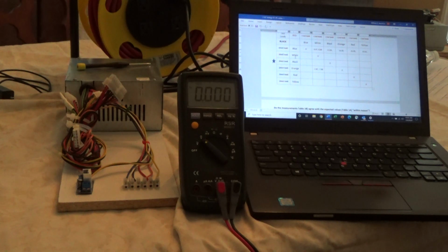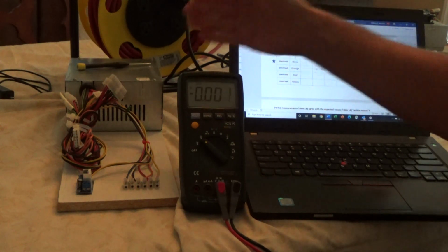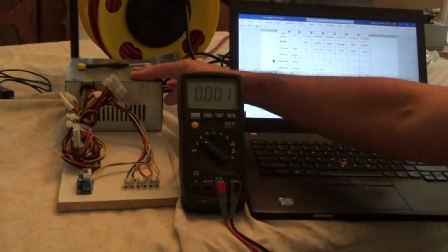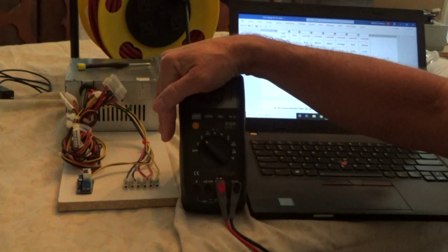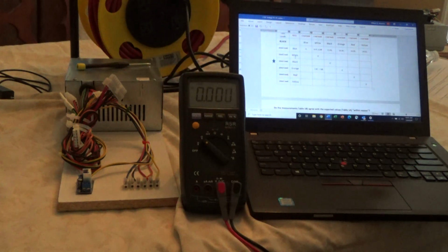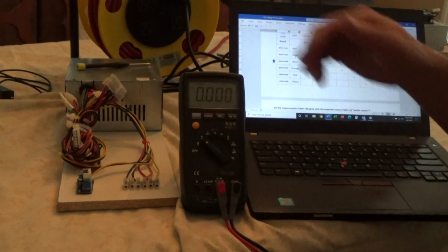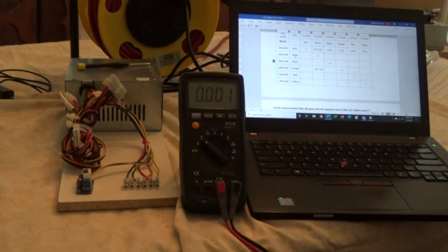Now, I just want to make a couple more comments. These computer power supplies are useful for other reasons too. For example, the positive rails will deliver a pretty substantial amount of current. Your car battery is 12 volts. An old car battery is 12 volts. Now notice we have a 12 volt rail here with significant power. You could buy a cheap audio amplifier that goes into your car and hook that up to the yellow rail and that'll power an audio amp. We do that a lot because audio amplifiers are useful for working with low frequencies when you need power to move something, in an AC fashion, something that changes, some movement like a piston or a speaker or something.